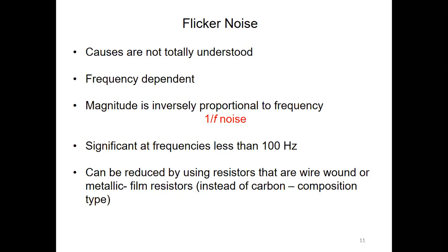Since it is inversely proportional, as the frequency gets lower and lower, the magnitude of the noise gets larger and larger. Therefore, when the frequencies are less than 100 Hertz, a significant amount of flicker noise will be in the signal.